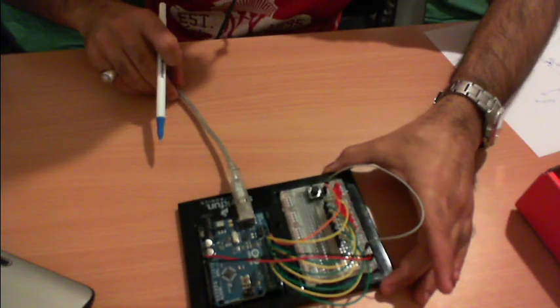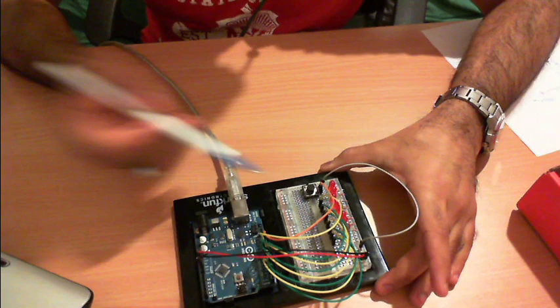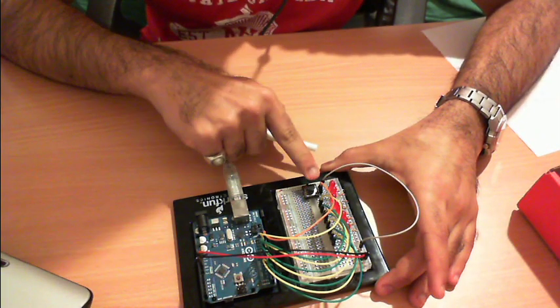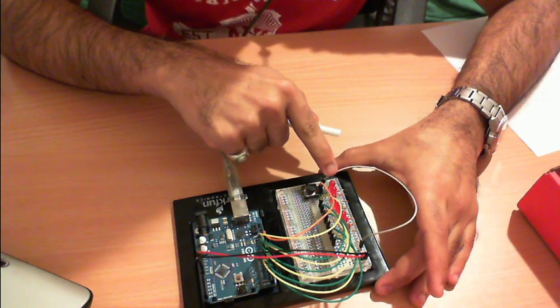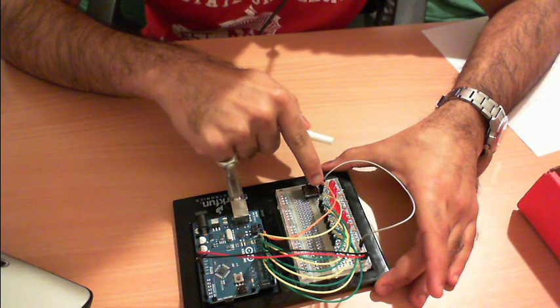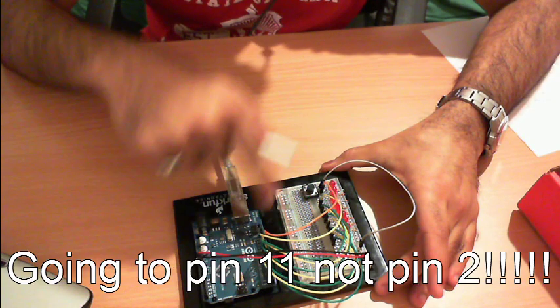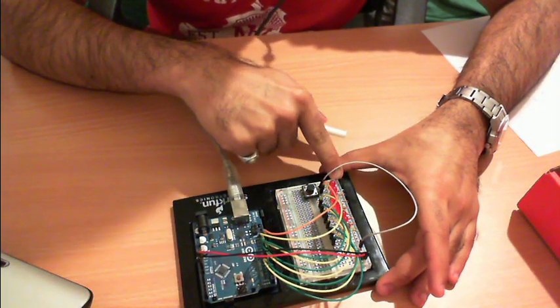Okay, so I've actually wired everything up here. So I've got my button here, and then I've got the resistor, the 10 kilo ohm resistor on this side going to the positive, and also going to the connection on the button that's going to pin 2 on the Arduino board. And then I have the other side of the button connected to the negative rail.